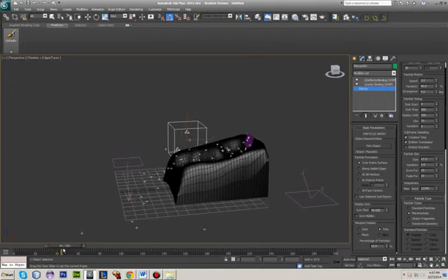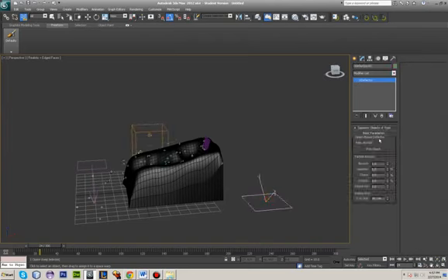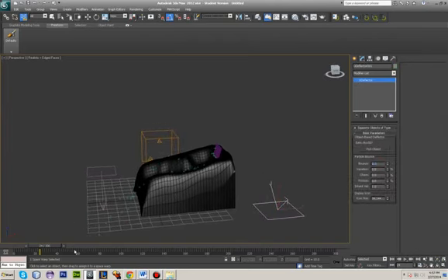And this is what I'm talking about. You can see the particles just bouncing once they hit my object. So I need to change the bounce to 0. Once I do that, you can see that it's a little more natural flow of water.